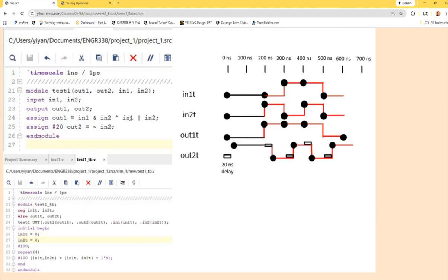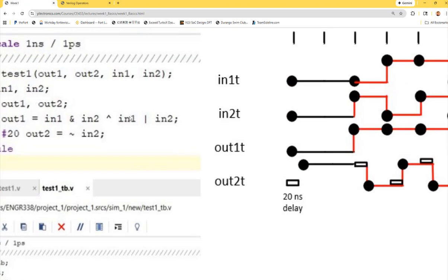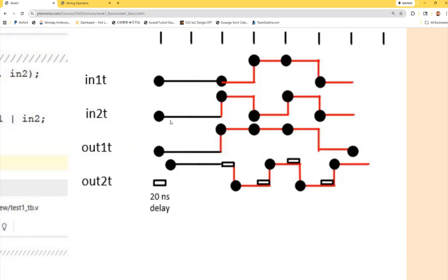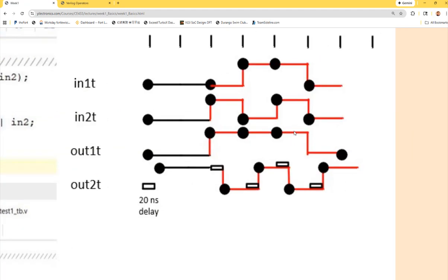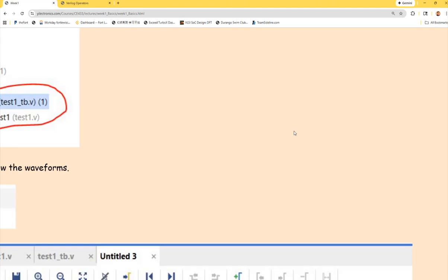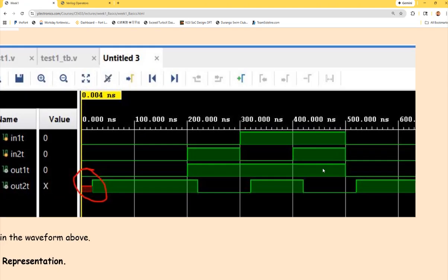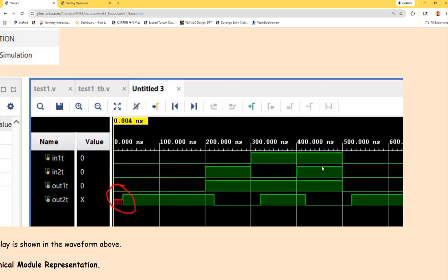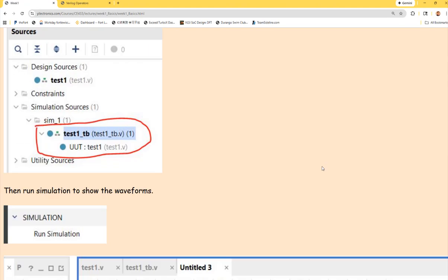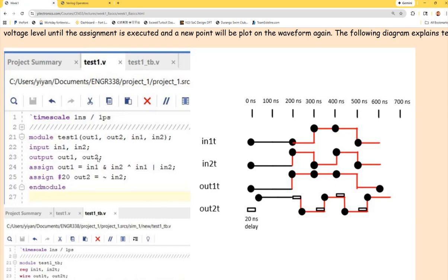However, if we follow the sequence, like what Luke just suggested, it's going to be AND 1 is 1, right? And 1 XOR 1 will be 0. And 0 OR 1 will be 1. And that works. And that might be how it's actually being executed in Verilog, in Vivado, because I directly used the code, I didn't change it. You can see the code over here in Vivado. But that's good to know.